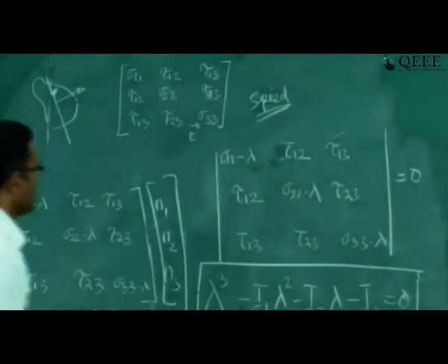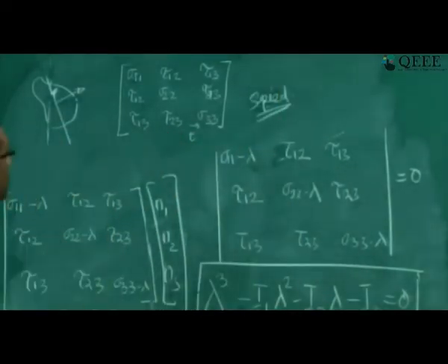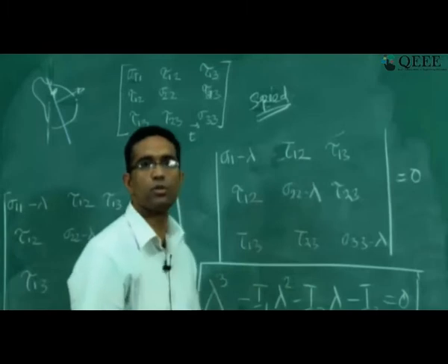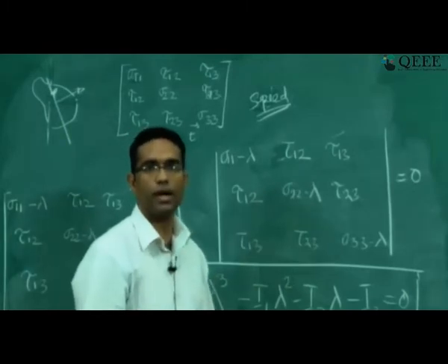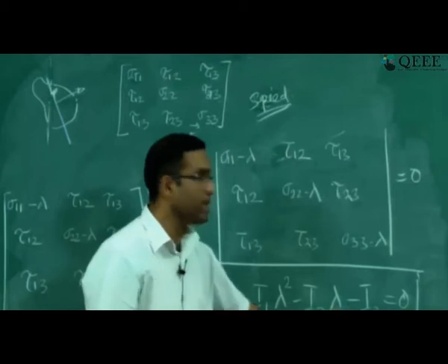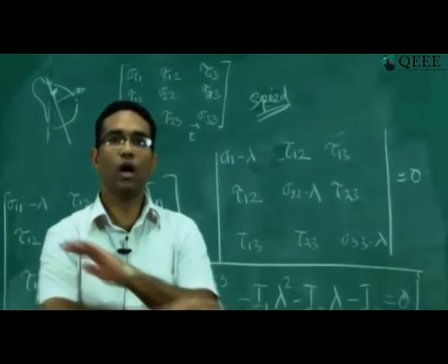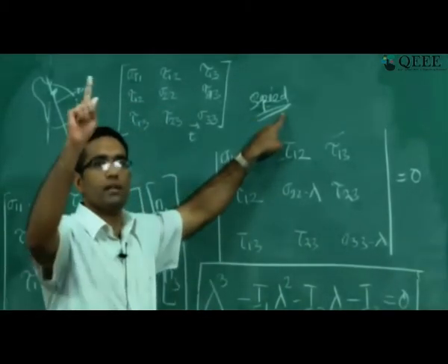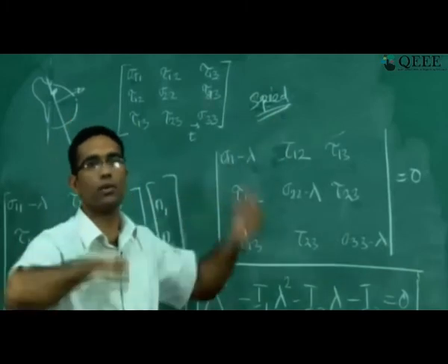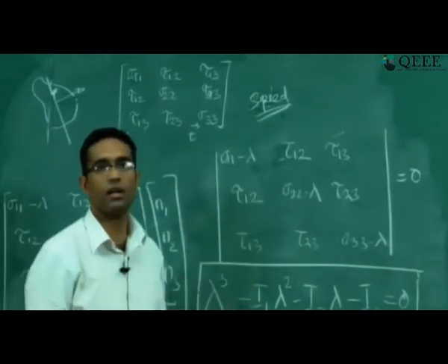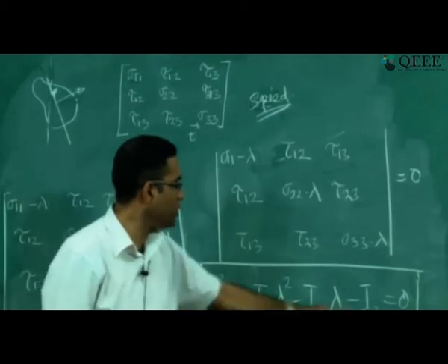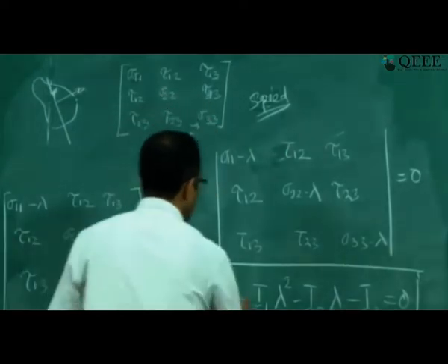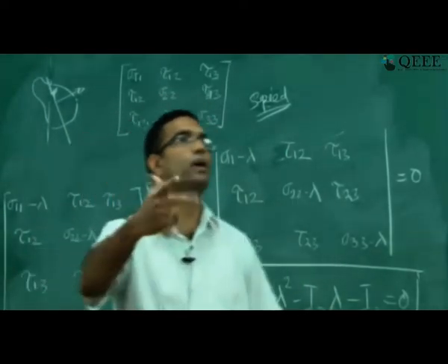In a similar spirit, for this physical quantity, which requires 2 directions and 6 different numbers to specify its state at a given point, you have 3 different numbers which will not change no matter how you rotate the coordinate system. For velocity, there was one invariant. The speed was invariant no matter how you rotated the coordinate system, right? For the stress tensor, there are 3 invariants. I1, I2 and I3 are the 3 invariants of the stress tensor. They will not change no matter how you rotate the coordinate system.